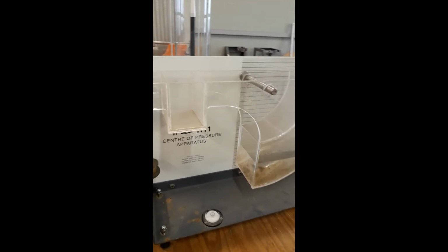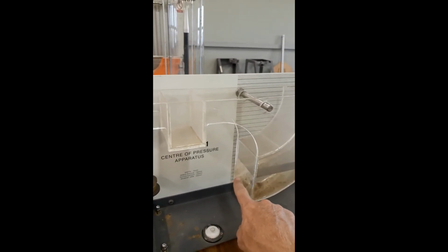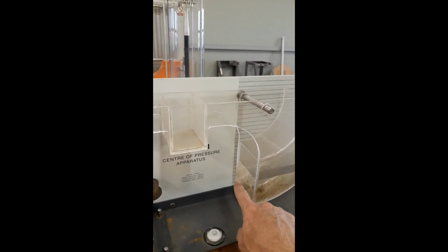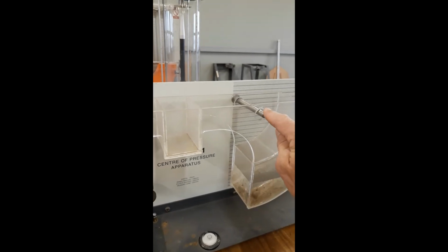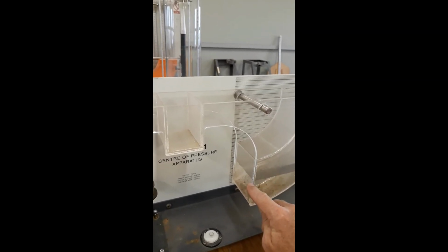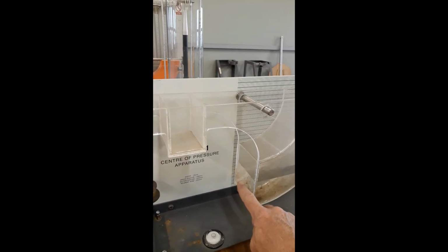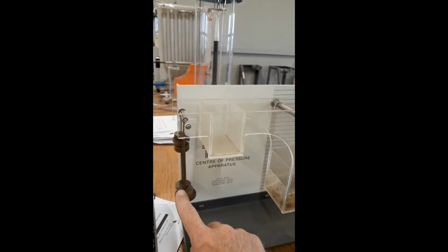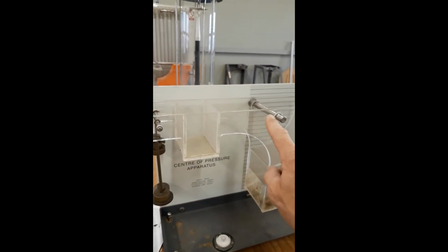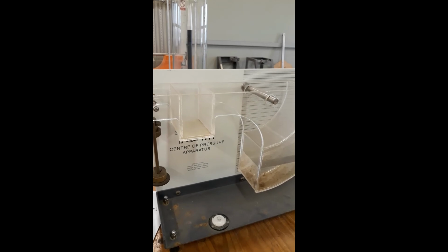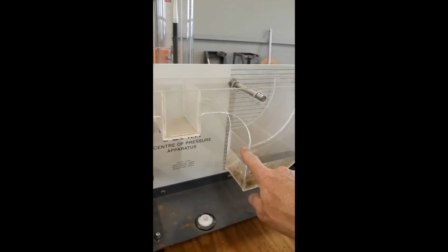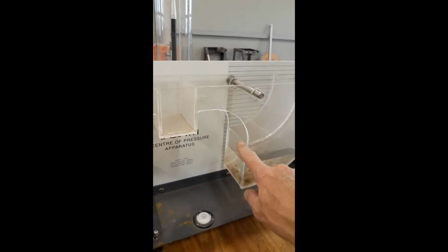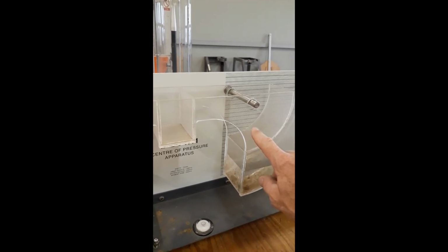So what does this all mean? We know the force will act at the point of COP. So if we add depth 1 plus depth 2 plus depth 3, we know where the force is acting. And we know the weight, and we know the distance to the pivot point. So we can use the equation of moments to calculate the unknown force. This procedure will repeat itself until this surface is fully immersed, with some extra additional points as well.